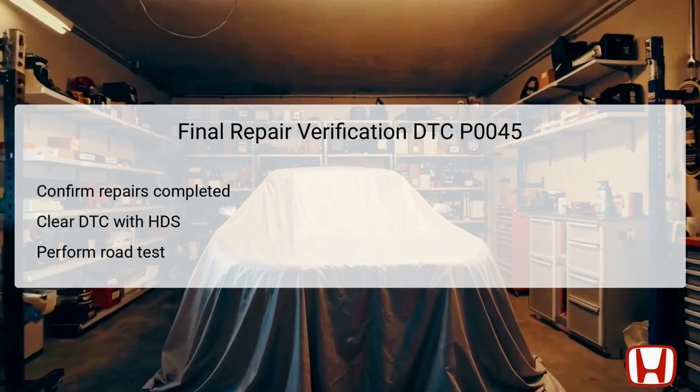Next, use the Honda Diagnostic System, HDS, to clear any lingering trouble codes. Following this, conduct a road test to confirm that the vehicle performs optimally and that the symptoms associated with the DTC have been resolved. Monitoring the vehicle during various driving conditions will help ensure the effectiveness of the repairs performed.